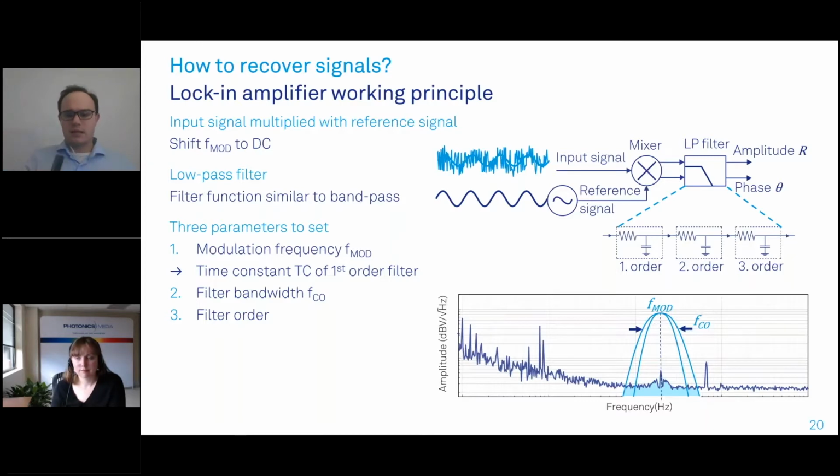On one, you send the signal, and on the other, for example, you send another laser beam, which you pick up before your experiment right after your laser source. What happens then is those two optical inputs are basically subtracted. This is why it's called balanced in the detector itself. And as a result, you only see the difference.